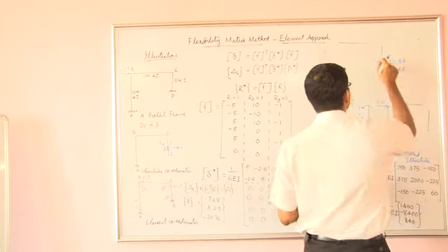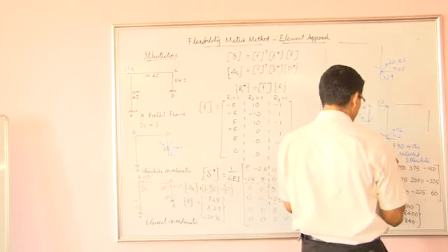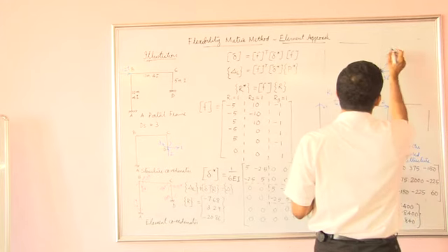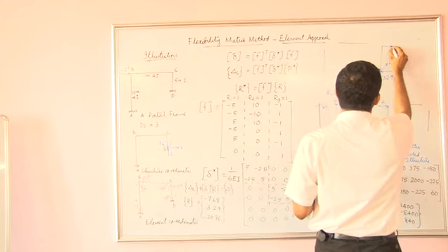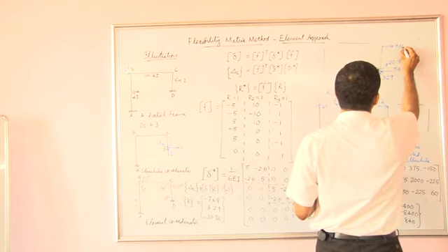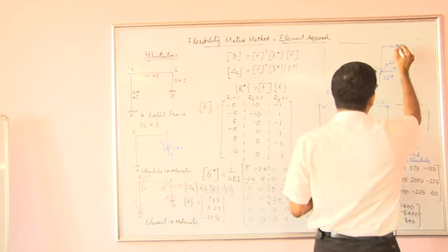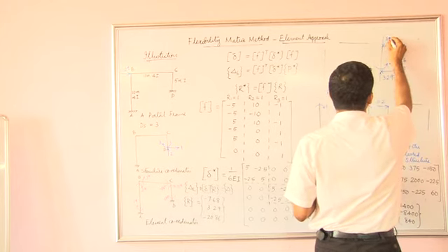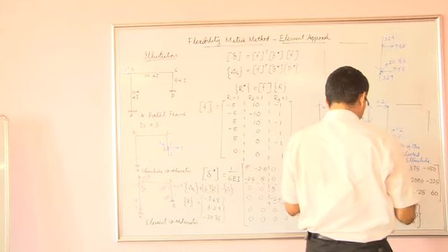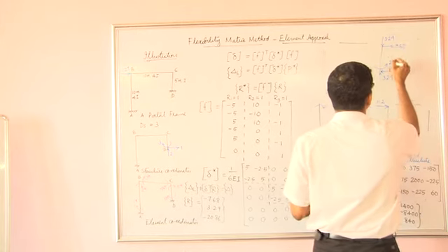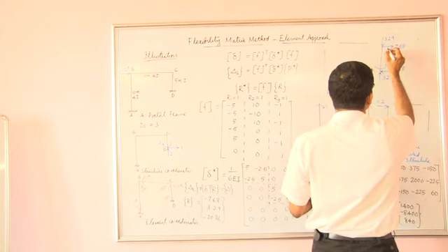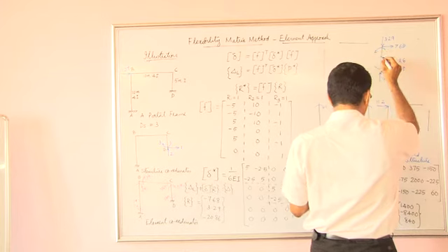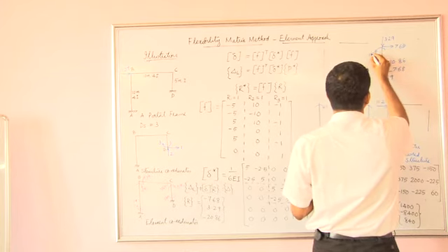So equilibrium at the other end would necessitate a force of 7.68, a vertical force downward 3.29, and an anti-clockwise moment of 17.64.